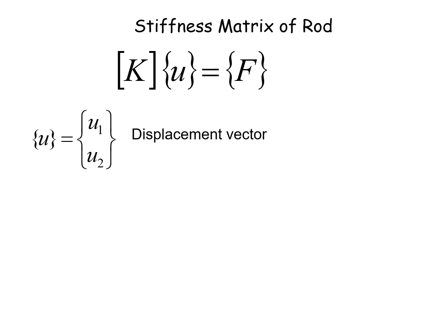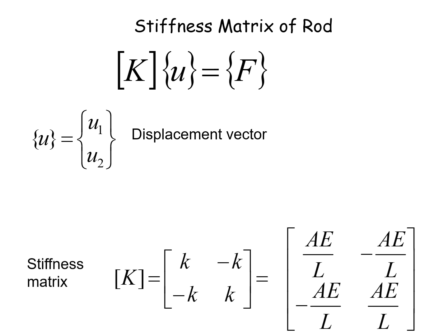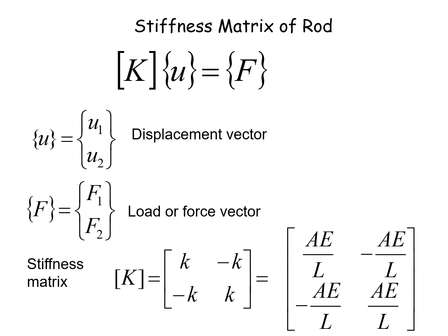U denotes the nodal displacement vector. K denotes the stiffness matrix. F denotes the nodal force vector. It is the fundamental equation for a single element in the stiffness method, and it serves as the basis for assembling a larger system of equations for a complete structure.